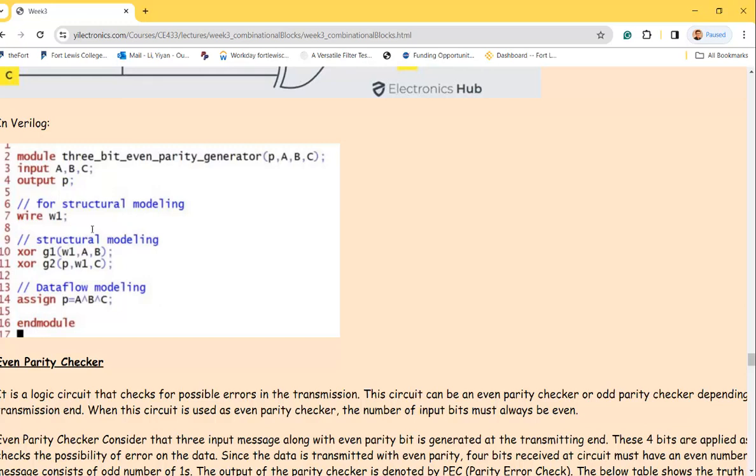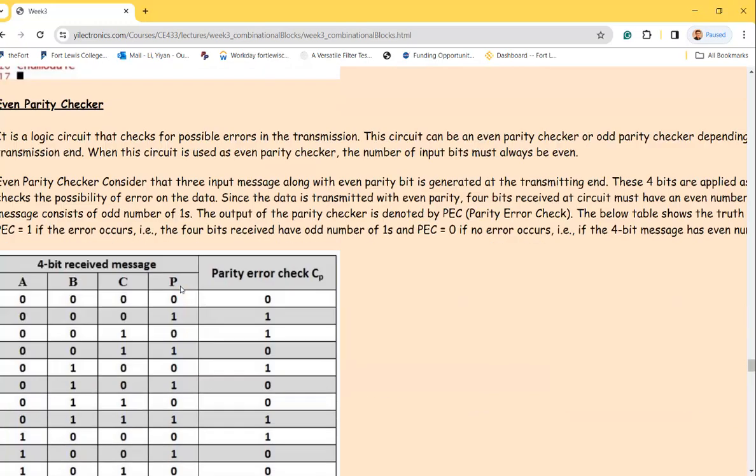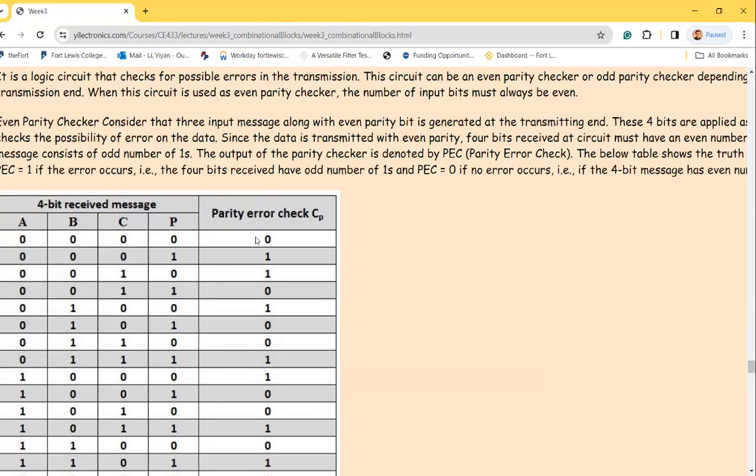So the checker is going to receive 4 bits, check these 4 bits, and have 1 result as well. So eventually, it's just 4 inputs and 1 output. That 1 output will be the error flag. So these are the 4 bits as input. If nothing is wrong, usually you give a 0. If something is wrong, you give a 1.